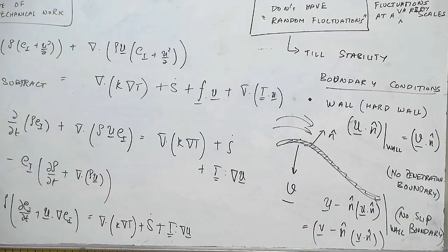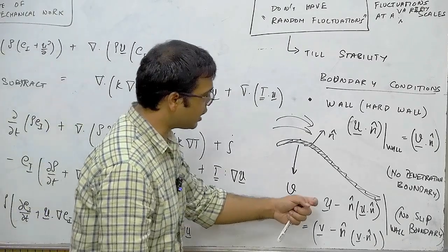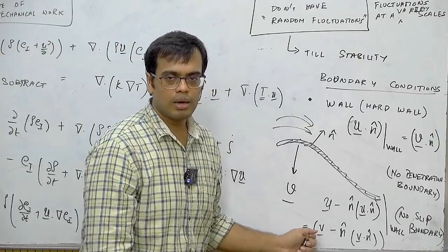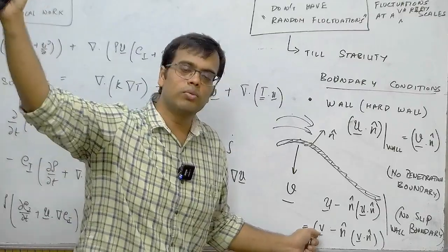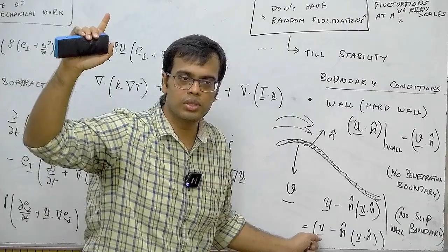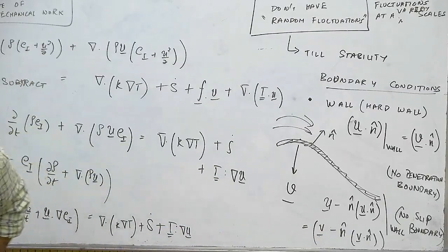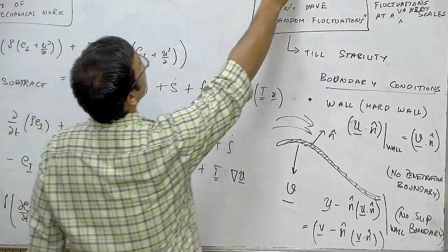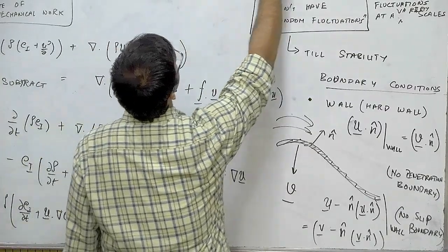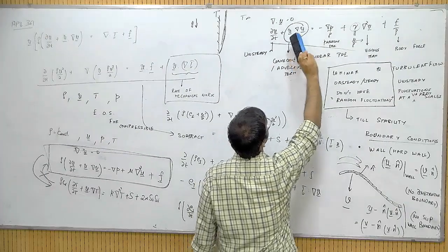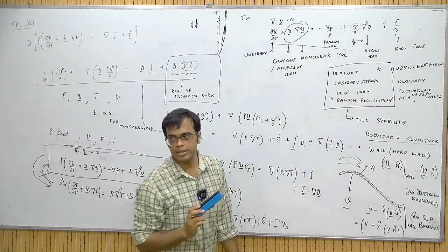Okay. And whenever we are discussing all of this, you should keep in mind that when we go towards modeling, when we go towards inviscid flows, we will encounter this question: which boundary condition to drop. Because when you drop viscosity, you will see that your partial differential equation remains nonlinear, but will no longer be second order.